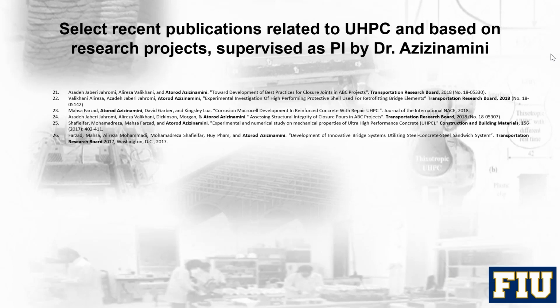And then in addition to that, if you want to strengthen it, you can add some additional reinforcement. With water pressure or sandblasting, you can remove the concrete and go below where the first layer of the reinforcement is. But you don't have to go too much beyond that. Even in the case of a column, for example, if you have contaminated concrete way beyond that, the recommendation that I heard from the Europeans was to remove no more than about 1 inch beyond the steel reinforcement you have. Okay.